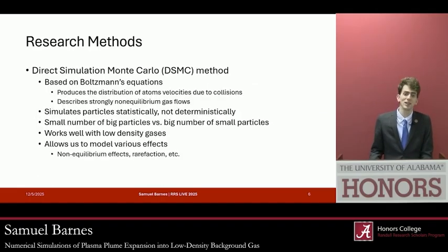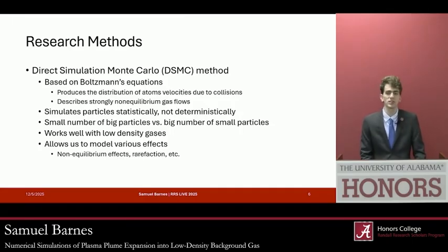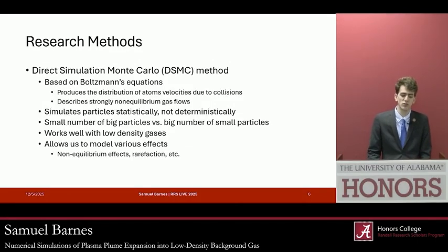Our method for simulating this expansion is going to be the Direct Simulation Monte Carlo method, which is based on Boltzmann's equations, designed to produce the distribution of atoms' velocities due to collisions rather than macroscopic temperature. This describes strongly non-equilibrium gas flows, so in our case it's useful.